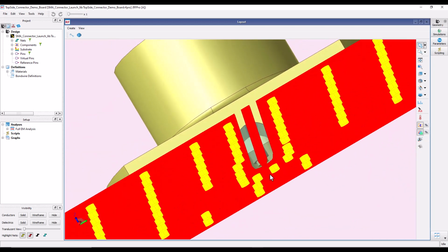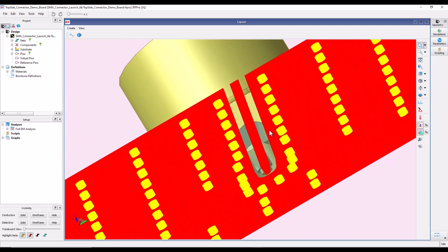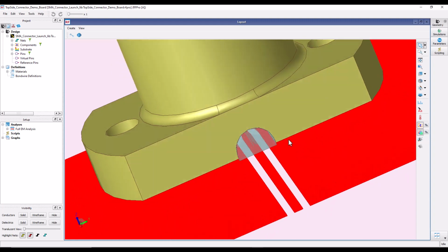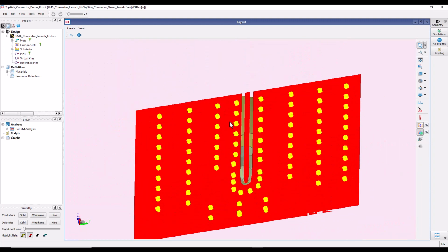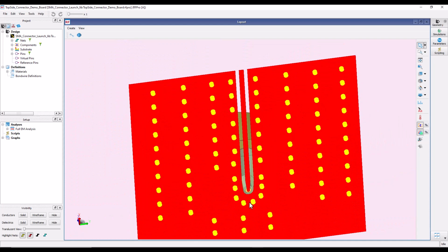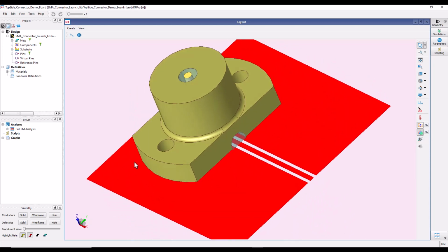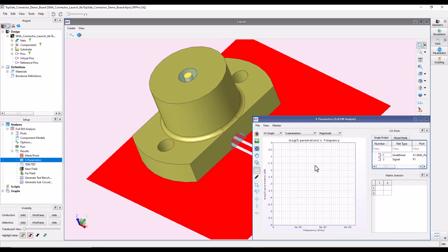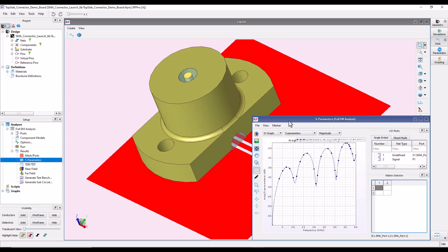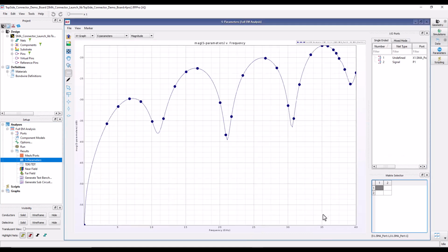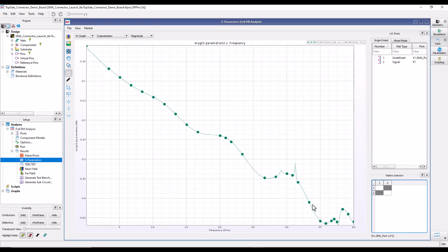I created something like a CPW with a via array and a lot of vias around the transition where this is happening from coax to microstrip. And again, we are going to talk about some of this in our next video. Now for this assembly, again, if you look at the response in terms of S parameter, you can see pretty good return loss all up to 40 gigahertz, and also the transmission response looks fantastic till 40 gigahertz.